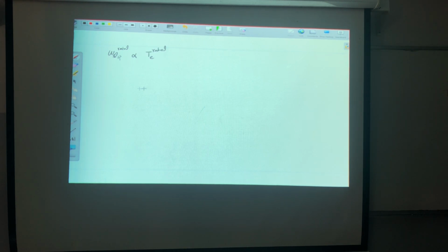So if I need to calculate any omega slip, which is proportional to any torque, omega slip will equal TE over TE rated multiplied by omega slip rated.